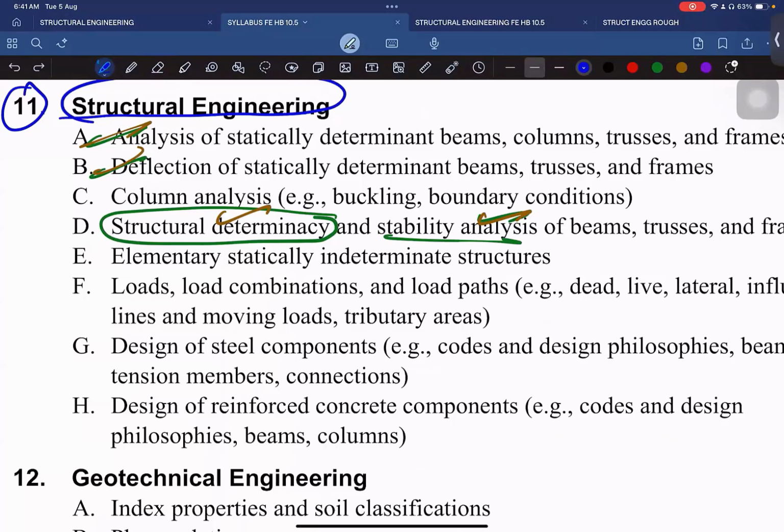Need not be. If it is structural steel, the buckling can be time taking. To be precise, crushing is sudden. Got it. And it has different combinations. Suppose concrete prefers to crush rather than buckle. And steel, obviously a very strong material, will not crush, it will buckle. Based on material and slenderness ratio, it varies.